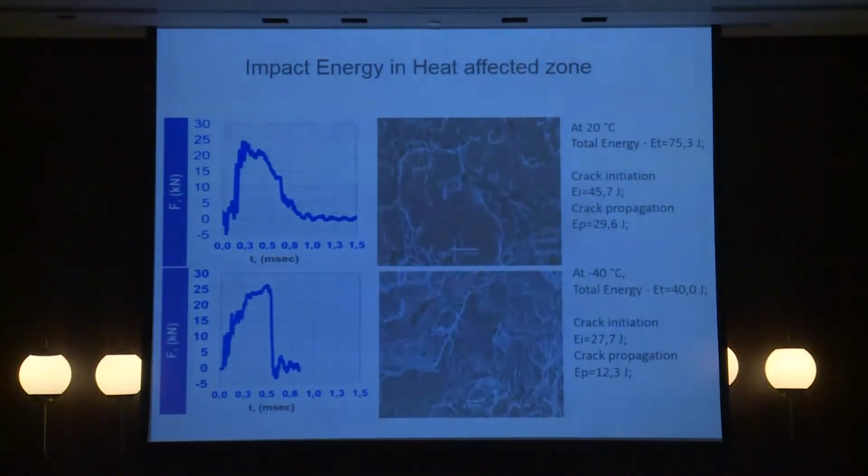As we can see, the fracture surface is a clear brittle fracture. We can say that both crack initiation and crack propagation energy show a significant drop. Crack initiation energy drops from 45 to 27, and crack propagation energy from 30 to 12 joules.